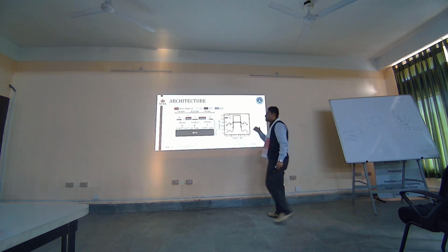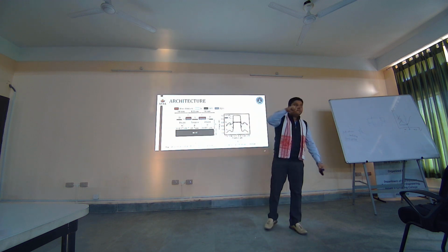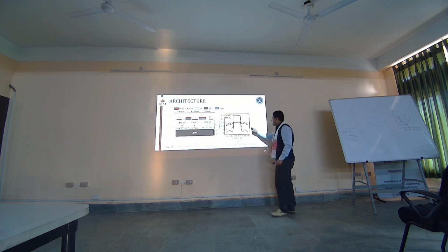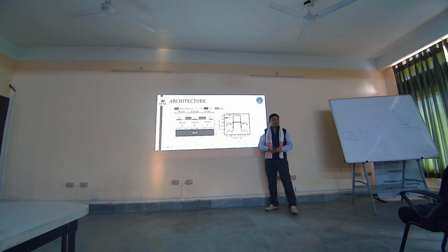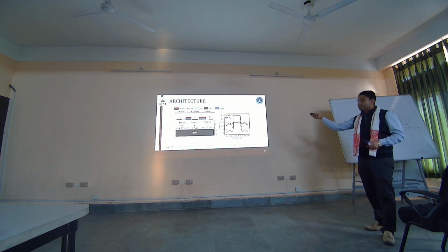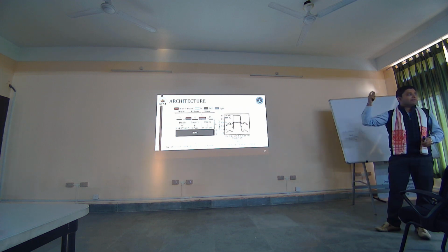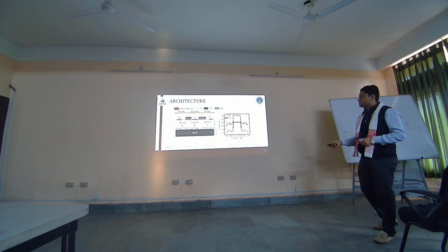Now, this was when we thought that this was going to happen, but we needed to test it, right? So then we calibrated it with an existing TFET, and we tried to see its energy band diagram first. If you observe, there are very good amounts of overlap on both sides, where you can have appreciable tunneling, and therefore you can have current. Okay, so this is one architecture which we did, and currently we are also working on this. We are also looking for fabrication possibilities, and this is fabricable. Although in a bigger diameter, this is a fabricable device.